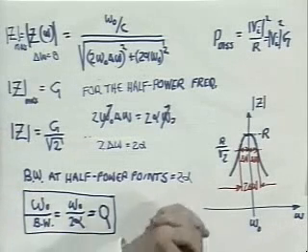If you have a resonant circuit, an RLC circuit, where the circuit is underdamped, the resistor is quite large, the conductance is small, alpha is less than omega naught, that circuit exhibits oscillatory behavior in the time domain. In the frequency domain, where you're driving the thing with a complex exponential at some frequency omega, it exhibits a resonant peak at omega naught, if alpha is small enough. Actually omega d, but if alpha is small enough, the two are equivalent. It exhibits a resonant peak in the frequency domain.